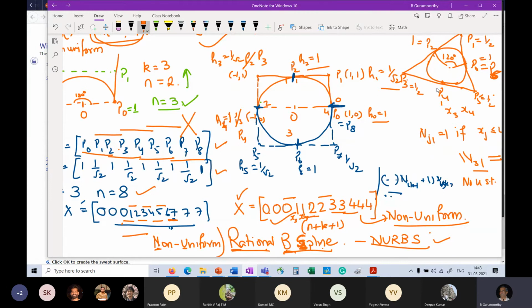I can define a circle with 7 control points. I can define a circle with any sort of division of 360 degrees, right? So as many. So if I want divided by 60, I will get that many segments, right? 90 I got 4, 120 I got 3, 60 I will get 6, and so forth. Right? And all of them will be valid representations, except as somebody just said, you will have more control points. So if you have 9 you are not happy with, you can go to 7, right? And if you want more from 9, you can go to whatever number you get for the 60 degree included angle.